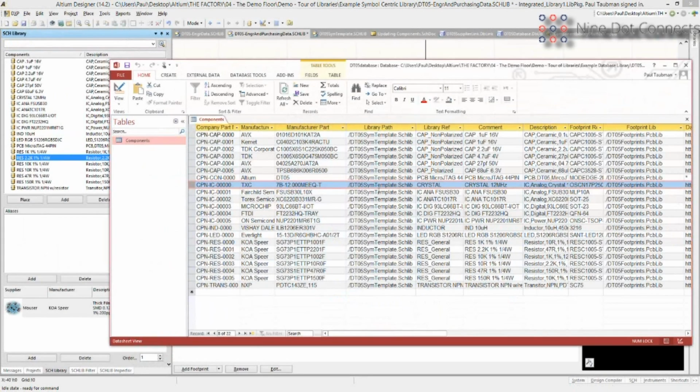By putting in this particular library path, I make it dead-on specific. In this schematic library, I want this part, end of story. Don't go looking at anything else. So that's why I'm a big fan of being very specific about calling out the library name that needs to be used for both the footprint and the symbol.